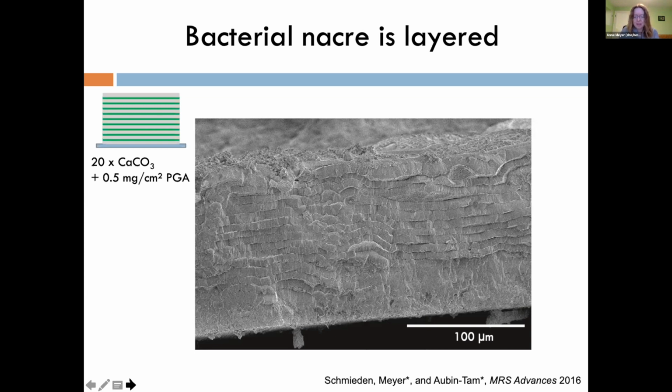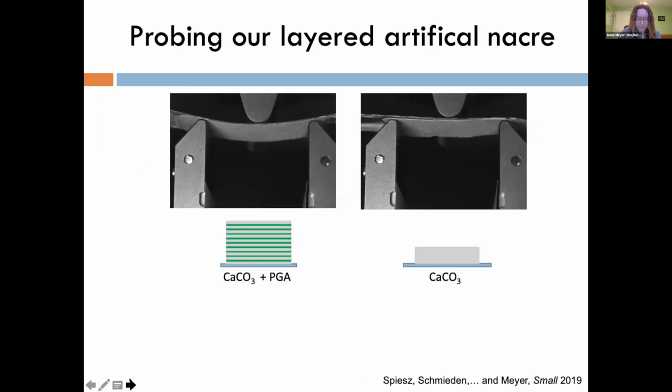So Ava on the project had a great material science background. She did a lot of mechanical characterization of the properties of our material. Here's one example of the kind of test we did. This is a test looking at fracture toughness. So, how far can you bend it before it starts to crack or fracture? This is called a 3-point bending experiment. Basically, there's two platforms on which you balance your material. That's like the 2 points of the 3-point bending experiment. And there's a probe that comes from the top at a certain defined force. And then you can see the deformation behavior and cracking behavior of your material over time as the probe interacts with your material.